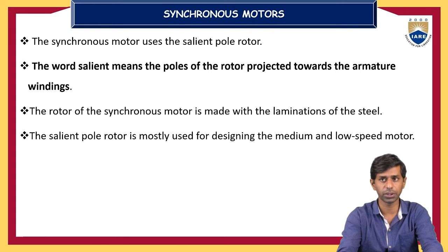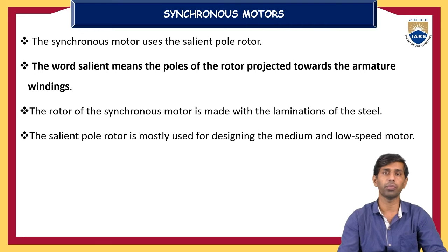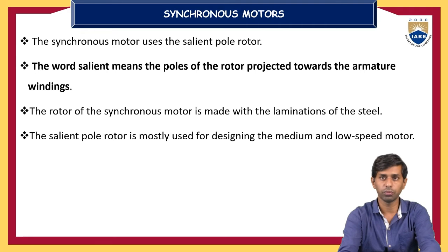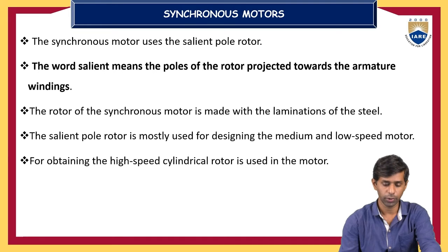For any kind of machine, whether it is an induction machine, a synchronous machine or a DC machine, the lamination thickness depends purely on the operating frequency of the machine, that is the rated frequency. Generally, it is a 50 Hz rated machine, where the lamination thickness may vary between 0.3 mm and 0.5 mm.